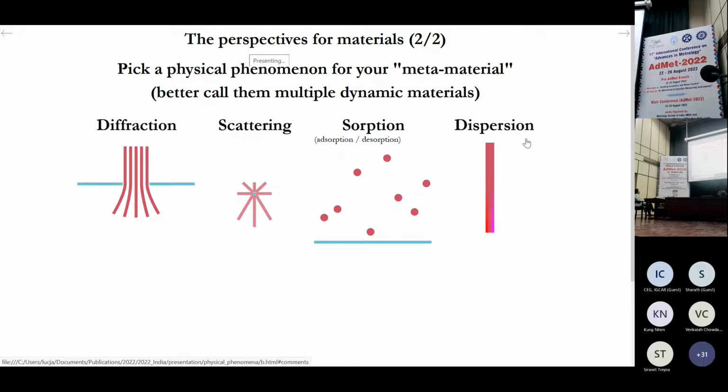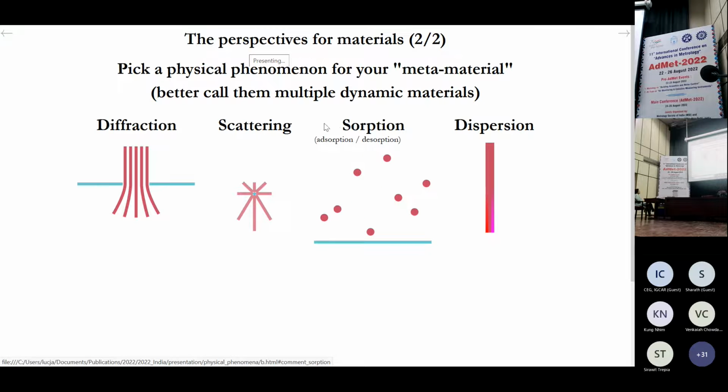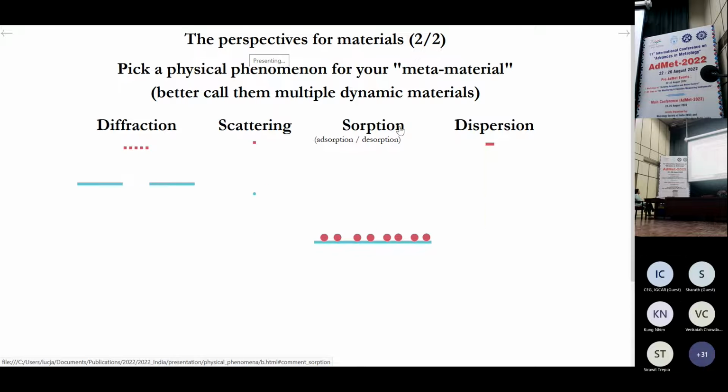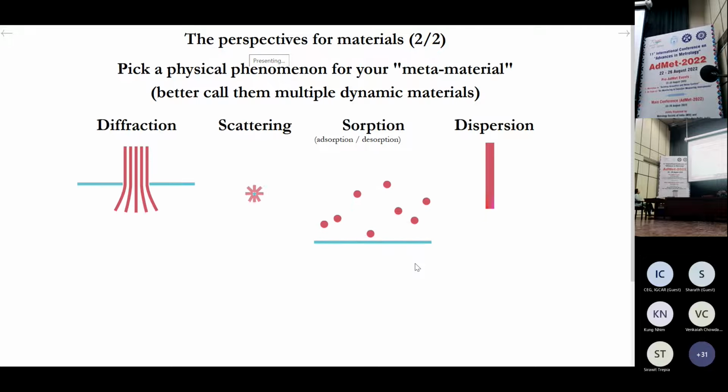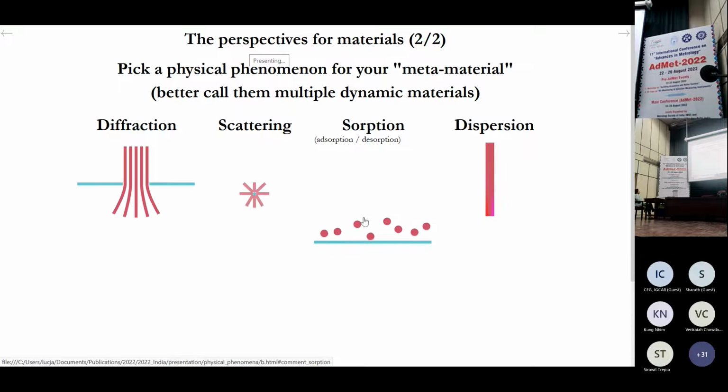So we have seen that rho and k are a function of the frequency, but you can also take into account or add some dispersion inside the solid phase. And for the absorption, this is not a wave phenomenon, but a mechanism made of adsorption and desorption. Adsorption is the possibility for the solid part to glue, if you want, the molecules of the fluid. And this is what we find, for example, in activated carbon.